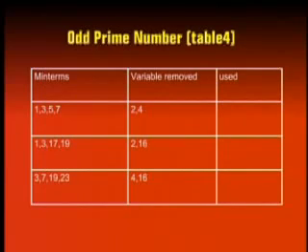The results of the comparisons between 2 terms in table 3 are represented in a separate table referred to as table 4. The first column lists the terms that have been compared together to eliminate common variables. So terms 1, 3, 5 and 7 form a single term eliminating variables C and D, forming the product term A bar, B bar, E. The comparison terms 1, 3 and 5, 7 are marked as used in table 3.